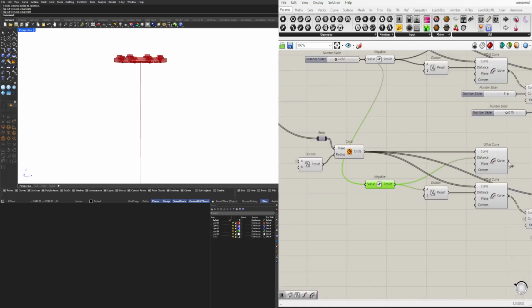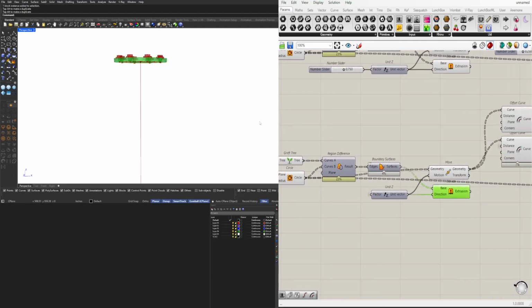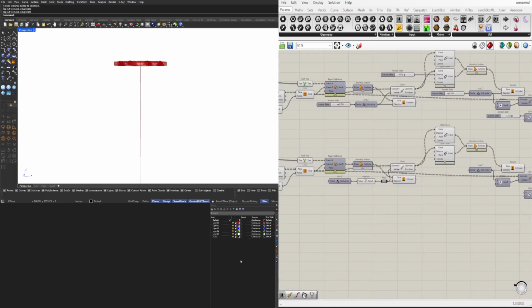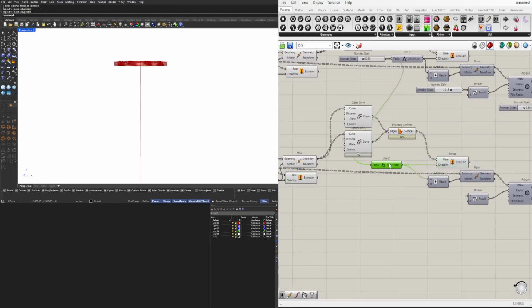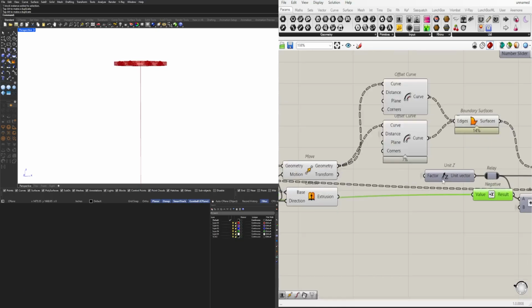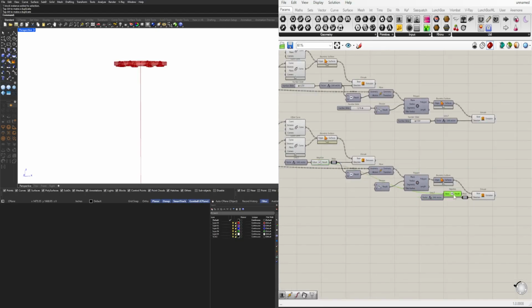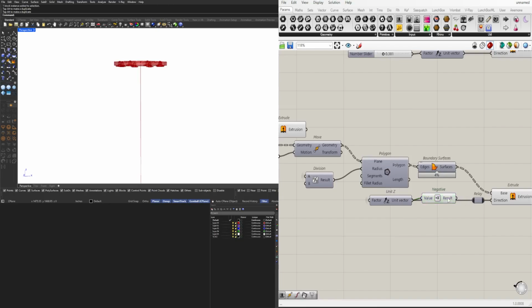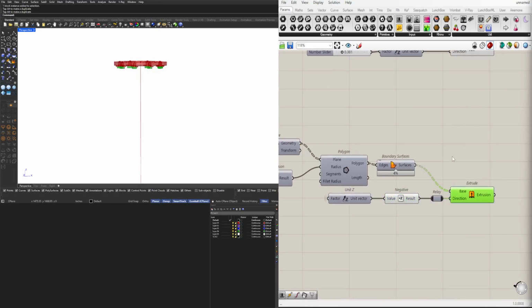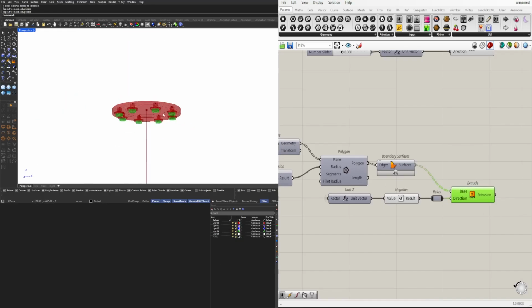All right, now that everything is hidden, the offset stays the same. This extrude, well, we go negative, double click here on the output because 2 wires are going into different inputs. And so now we can use a negative. Notice it now overlaps. This will also be negative. So create a relay, bring in the negative wherever you see a Z vector. I'm sliding it over, tapping Alt to create a copy. And now we have the exact same thing that we did down here, up here.